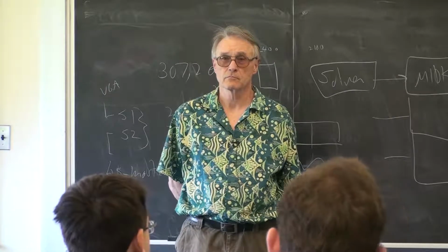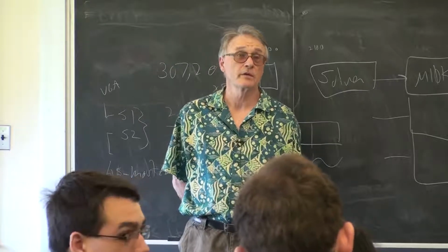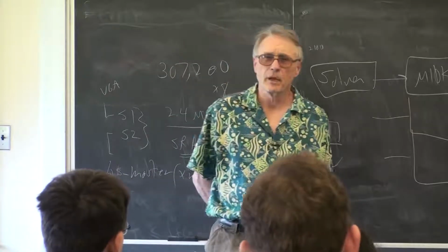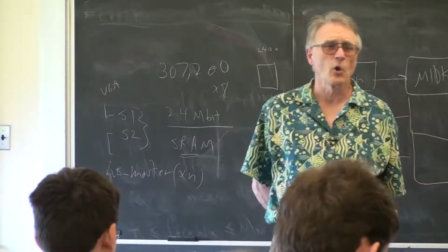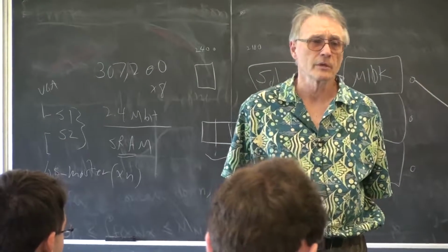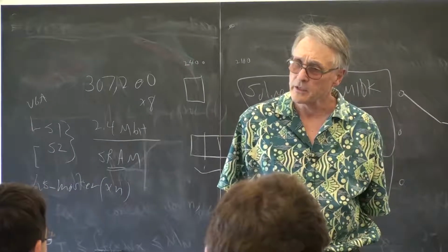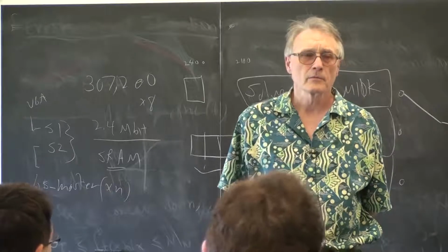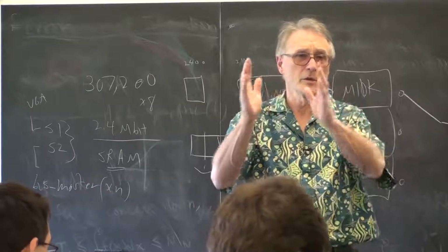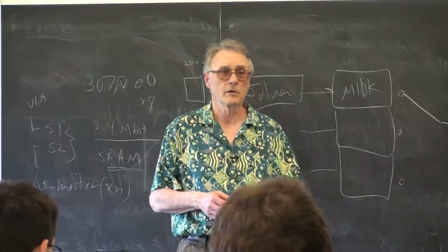If you configure the pins properly, you can also do LVDS directly from the FPGA. That is correct. You can do LVDS directly from the FPGA. You've got to go in and modify the properties of the I/O pin. I don't remember how to do that, but we can look it up. But that is possible. Do you remember how to do that? Yeah. Is it in the assignment editor? Yeah. So you open up the assignment editor and there's a pin layout there, and there's a whole bunch of properties that you can mess with per pin.